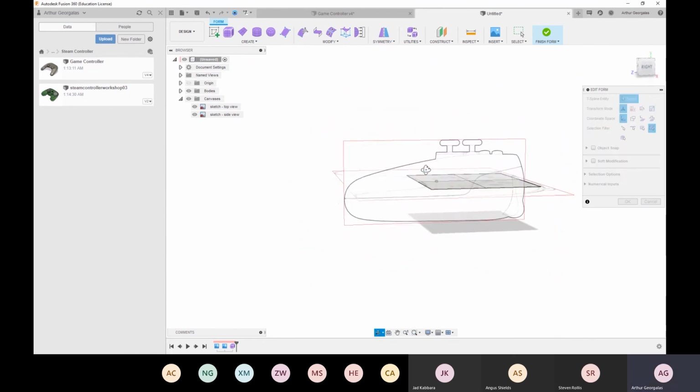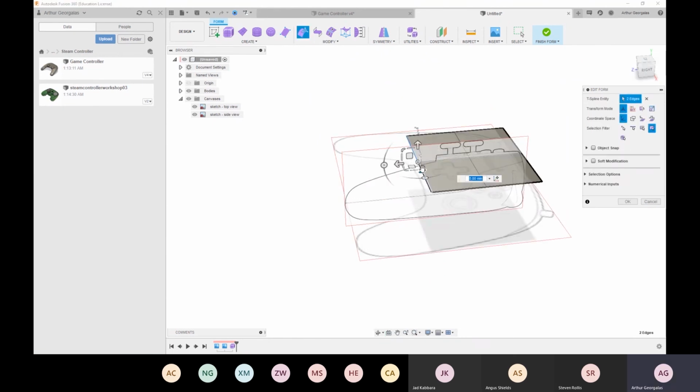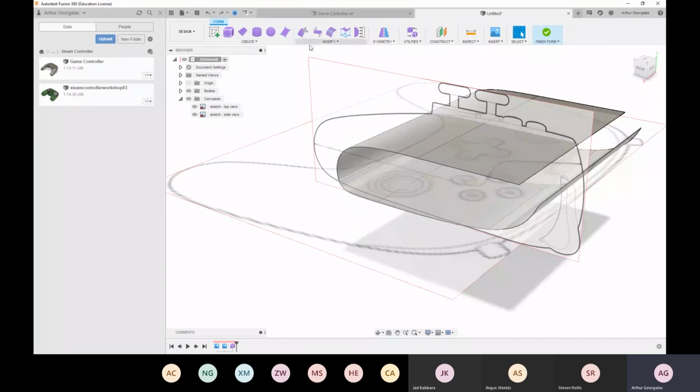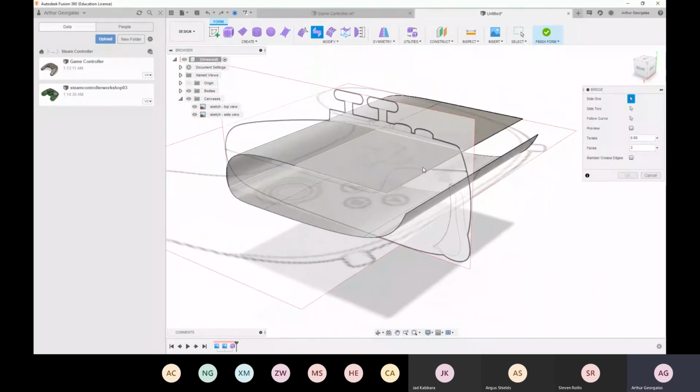Drag it to look right, bring it up, and then hold Alt, bring surfaces down, bring it around, all this kind of stuff. We could do that. And then we could bring it close and merge it like that, or we could even use the bridge tool, which pretty much makes a loft.